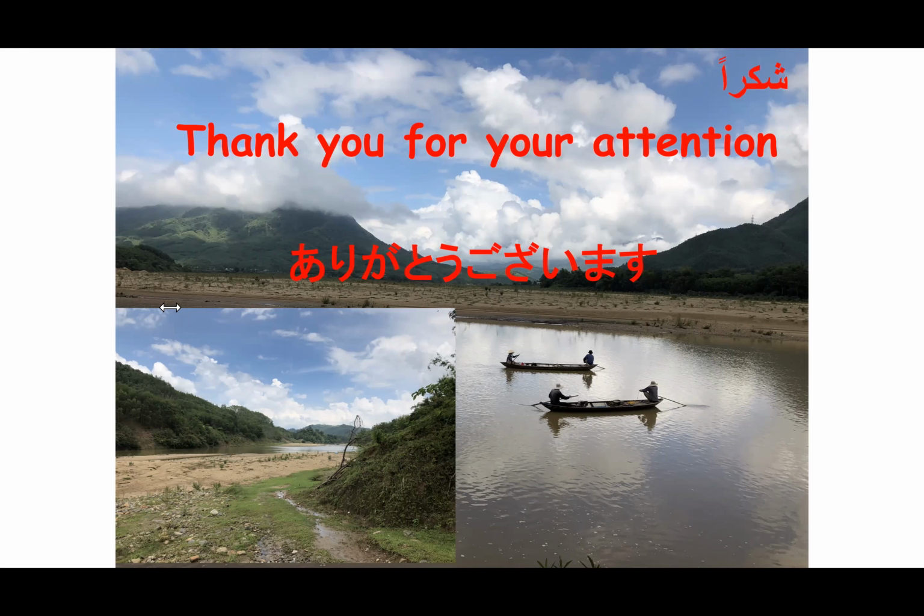We try to do that by numerical simulation and trial and error, because we have the bathymetry of the wadi reservoir in Wadi Mijlas in Oman. And we tried by trial and error in the numerical simulation to increase the sediment load slowly until we reached the same bathymetry, but that was really not so good an approach. But anyway, we reached that. We have around 35 gram per liter coming with one event.